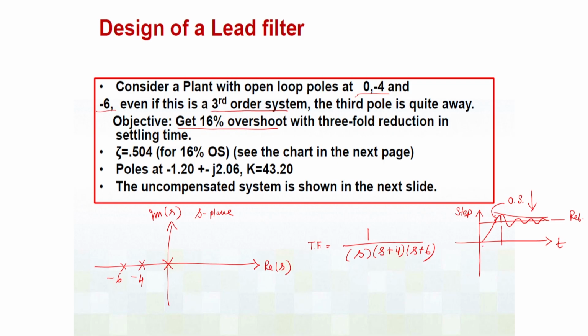Now, what is the settling time? Well, settling time is when this amplitude comes down from this, within, say, with respect to the reference signal, plus minus 2% of the value. There are two ways to define it. Some groups use plus minus 2%, some use plus minus 5%. So, settling time is this time. This is the settling time Ts, and it is generally written as 4 over zeta omega n, where zeta is the damping and omega n is the natural frequency of the system.